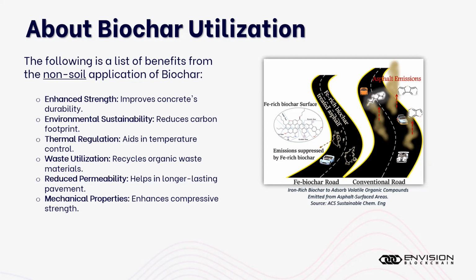So some of the benefits of char in non-soil applications are enhanced strength. So if you're using it in concrete, it could improve durability, environmental sustainability by reducing the carbon footprint, thermal regulation that aids in temperature control, waste utilization, reducing organic waste by creating biochar, reduced permeability that helps in longer lasting pavement, and mechanical properties that enhance compressive strength.